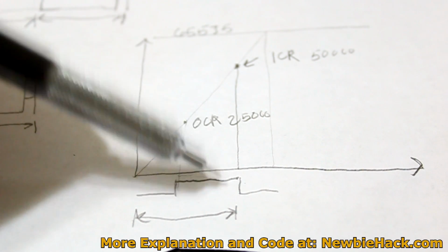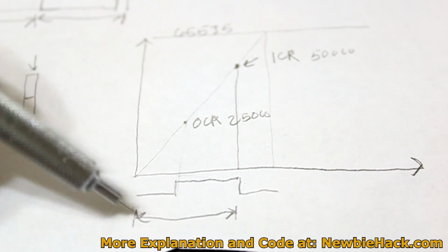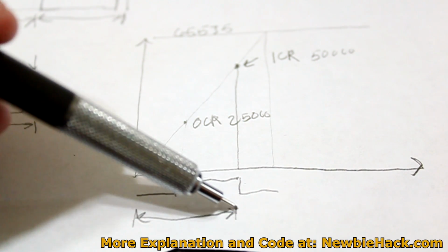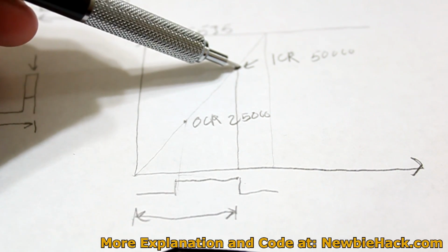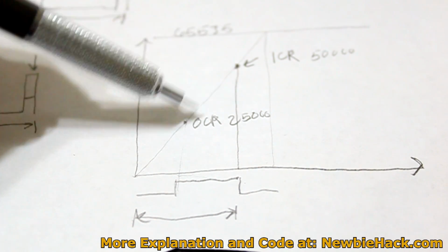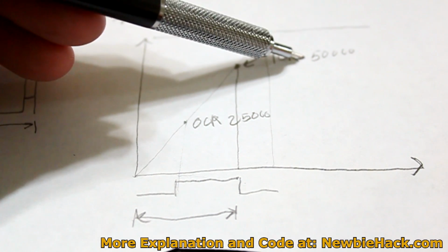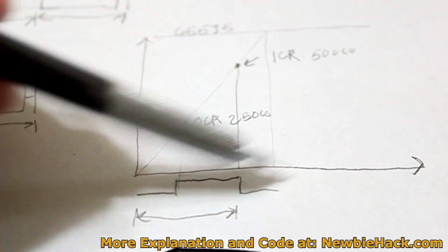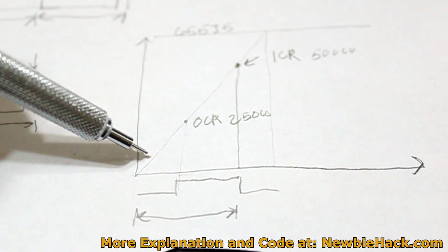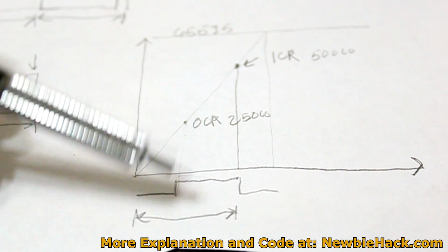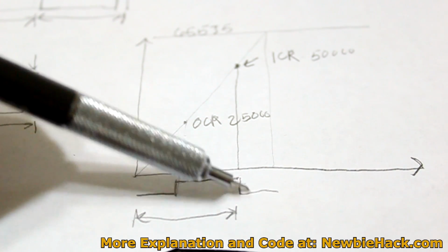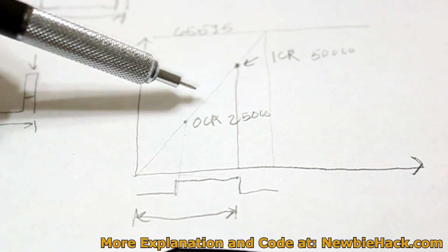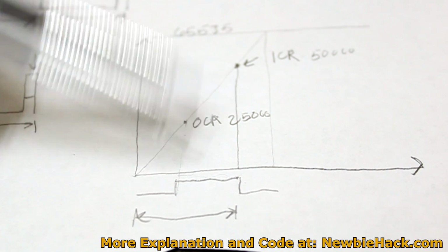And we can hit our period perfectly with 50 hertz or 20 milliseconds. And we can set that in only 2 registers, the ICR register and the OCR register, after we set up the timing control parameters. We can also take advantage of a manual approach to doing the pulses on any pin from the microcontroller using the timers, but we'll leave that also to another video.